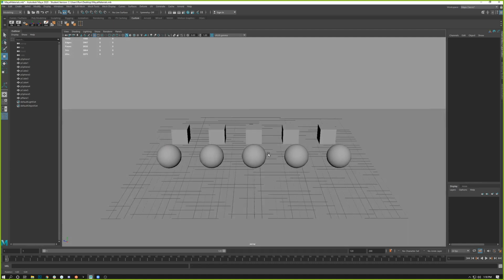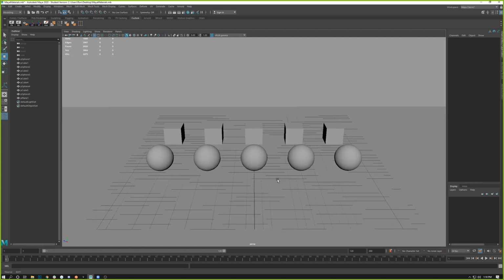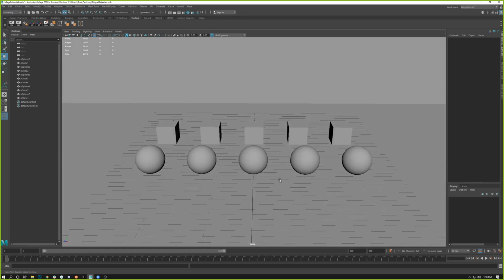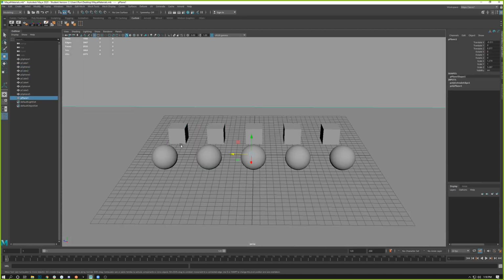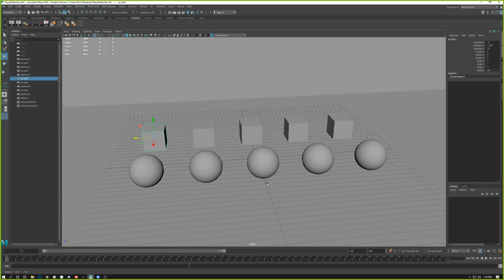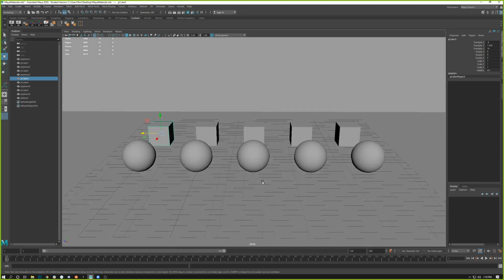So I'll do it wrong, or what I would classify as wrong, first, and then I'll show you the potential problems that you might run into if you do not create a Maya project. So I need to get materials on all these. We talked about materials in some other videos, but the basics still stand. What I need is every one of these objects to have a different material, because I don't intend to have any of them sharing a material. I would recommend sticking to Lamberts, Blinns, or Phongs. I would probably put the most emphasis on Blinns, to be completely honest, for this test series.